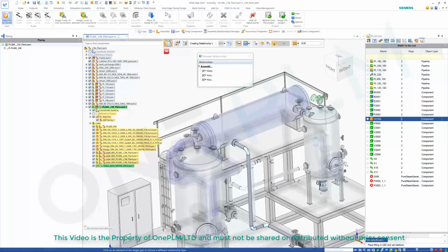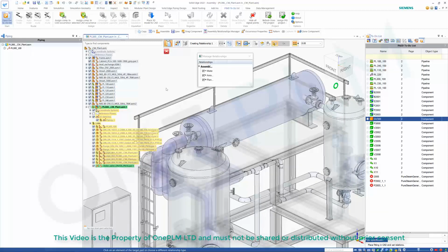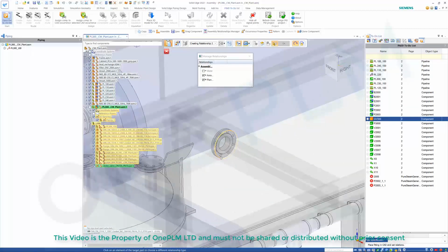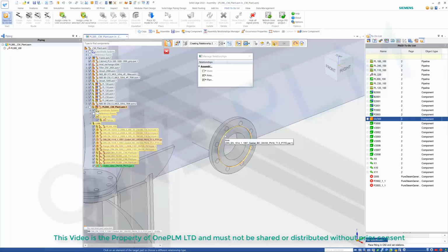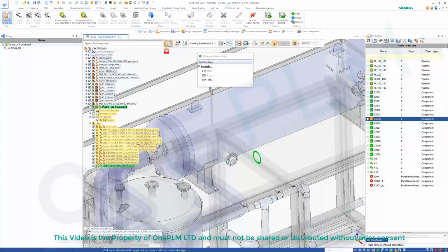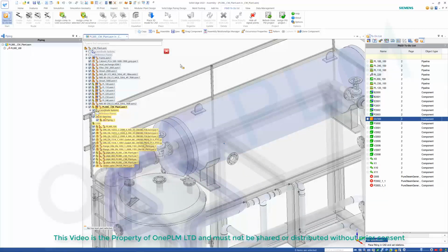Again, that has got some kind of mate on there as well. It's easier if we just turn that off. I find that nicer, so we can get that first relationship on there. So that's my first mate relationship. My second one is going to be this cylinder, and I need something for that to be parallel to. Notice all these options, or if I press Shift and click on there, that's going to allow it to create that relationship.